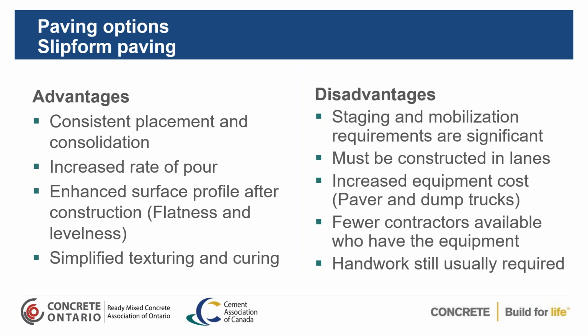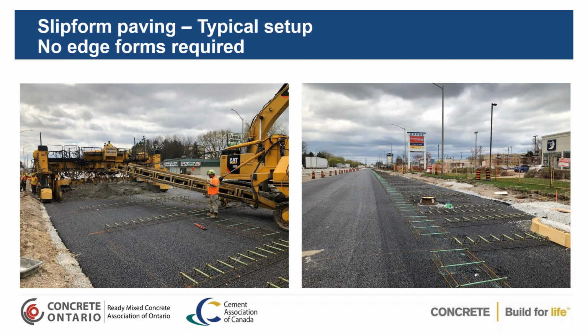You have an increased cost because you're not going to have your ready-mix trucks delivering the concrete. It's going to be dump trucks and you're going to have that paver. And you also have fewer contractors that have the equipment to do this. But in Ontario, we're lucky we have several contractors that can do slipform paving, but it is certainly less than the people that can do the fixed form paving.